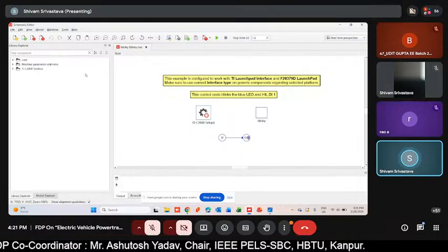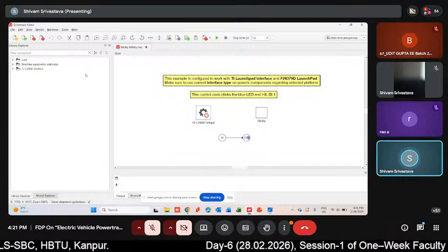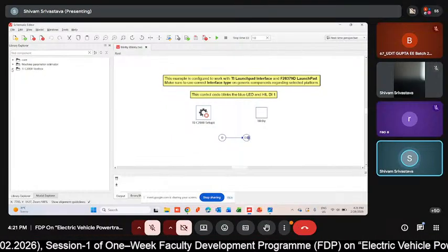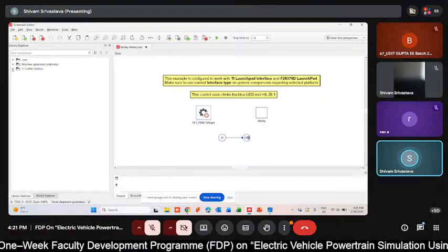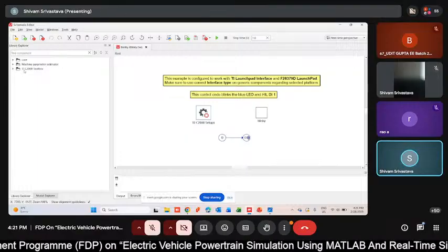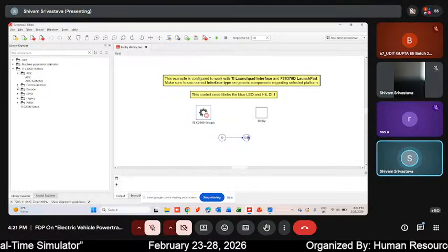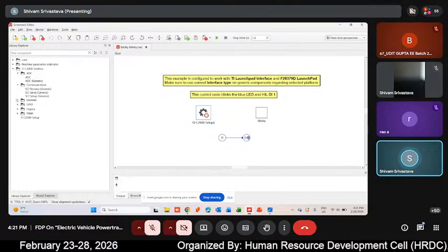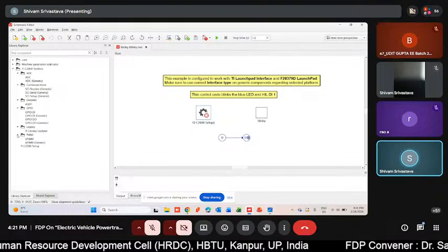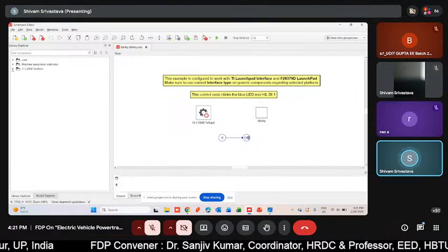I have already told you that once you install this particular package, some additional tools or components are added inside the library section. On the left-hand side, we have the library explorer, in which the very last folder appears by the name of C2000 toolbox. Once you drop it down, you can see various blocks such as ADC and ADC generic, communication, encoder, GPIO pins, legacy components, TI library updater, PWMs, and a simple C2000 setup block. We are getting all kinds of things.